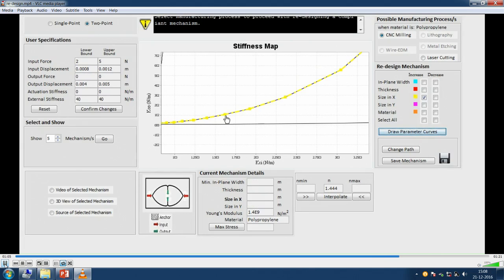So, now if you click any point on that redesign curve, you see in this particular case n range minimum is 6.34, and maximum is 8.64, and the mechanism point at that thing has 8.68, maximum is only 8.64, whereas you have 8.68 and that is in red color, meaning that n does not satisfy. So, you have to explore more along that curve, it is a redesign curve.